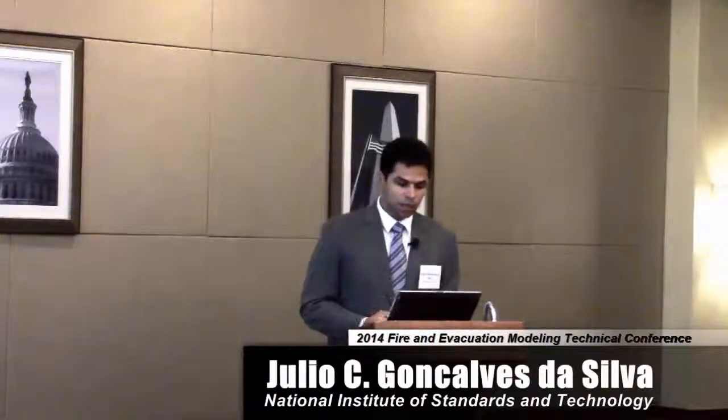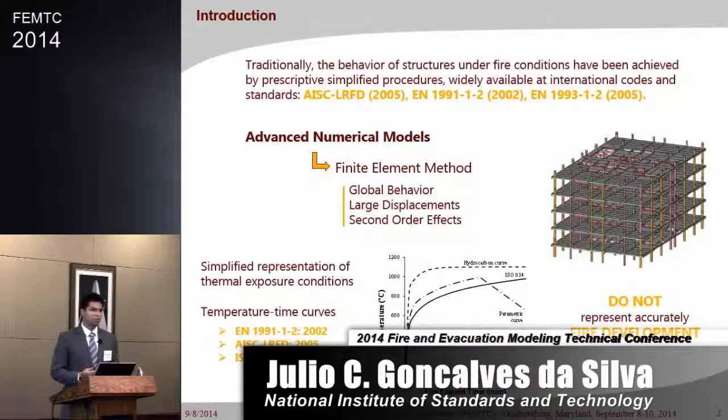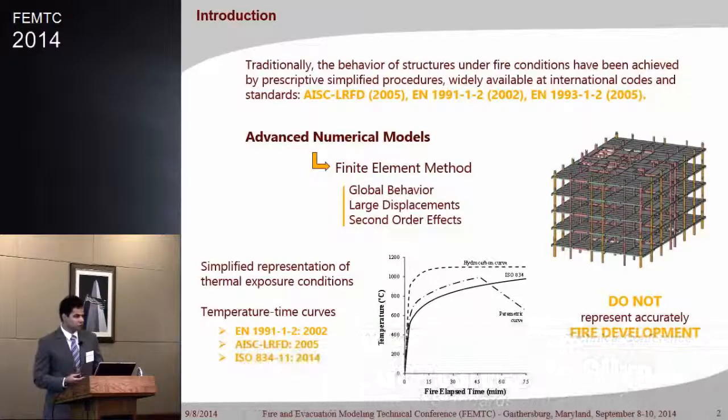So traditionally, the behavior of structures under fire conditions has been achieved by prescriptive simplified procedures widely available in international codes and standards like AISC or Eurocodes. Those codes are generally focused on checking if isolated members could meet the required fire resistance time.